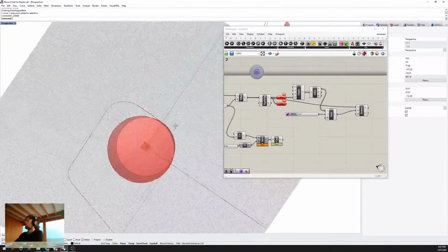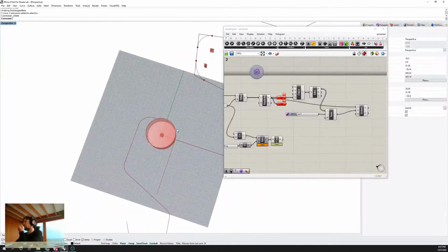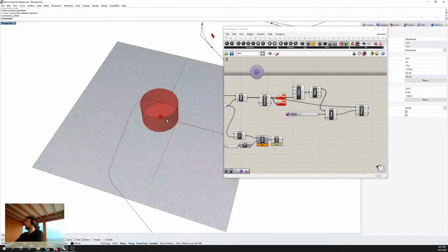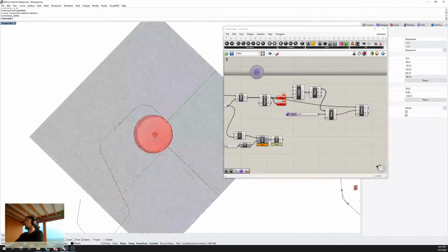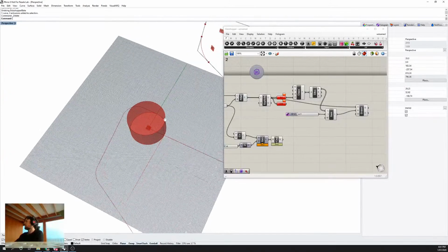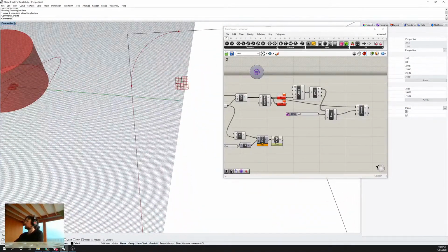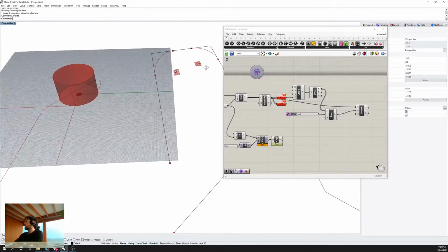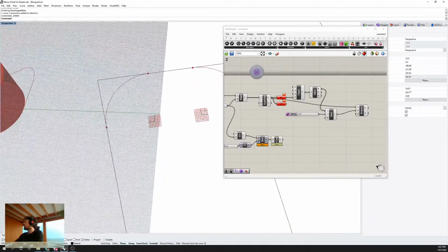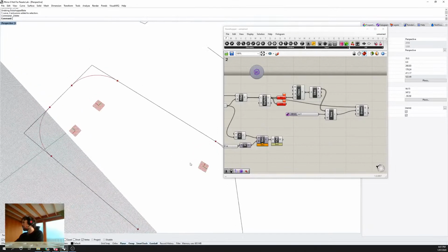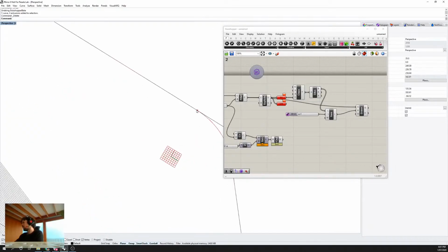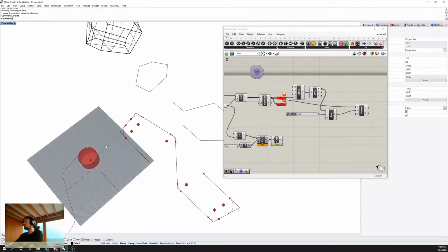Okay, so next step is to make sure that these bends are actually oriented properly. For now, what we have is we're taking the start point of the arc. You can see it's aligned here, end point of the arc. And I'm pretty sure the x-axis, I can't remember if the x-axis is always aligned to the start of the arc or not.